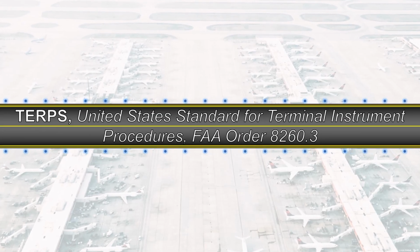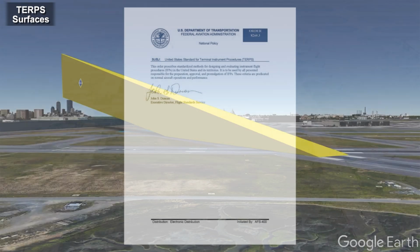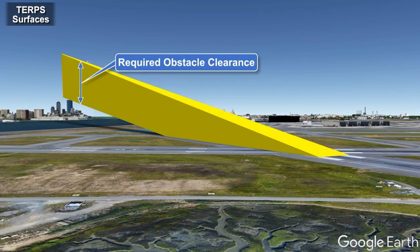TERPS surfaces. The FAA uses TERPS criteria to design and evaluate instrument flight procedures at an airport. For example, the development of a precision approach to a specific runway. TERPS criteria specifies the minimum measure of obstacle clearance considered by the FAA to provide a satisfactory level of vertical protection for instrument procedures.